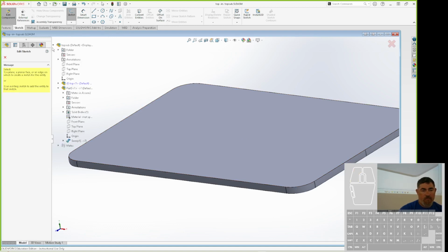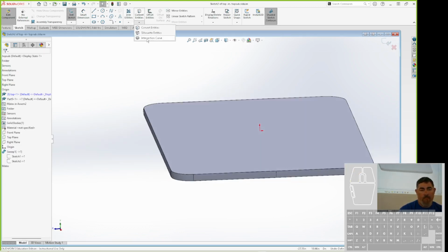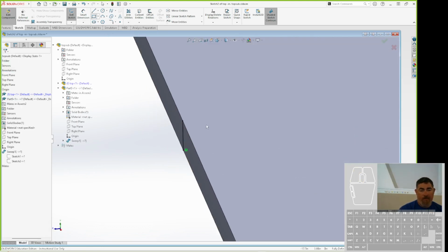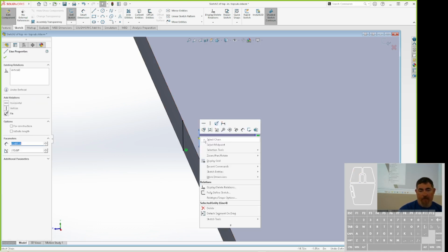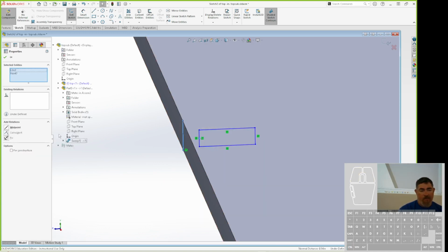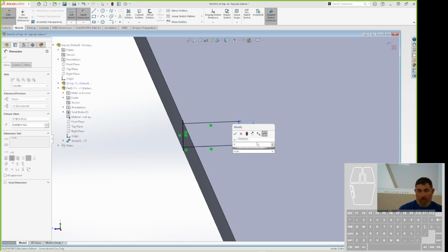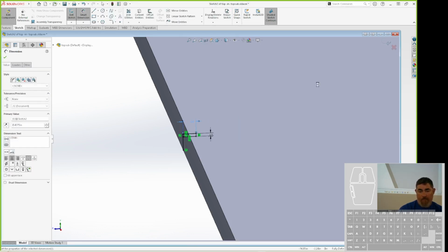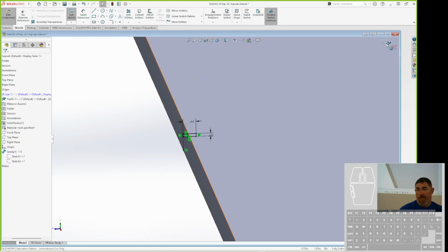Sketch. Over there. And then intersection there. And do my rectangle. And so I want to select the midpoint of this one. Grab that one, midpoint, dimension, said 0.1 and 0.4375. That's my depth. And that line is just going to be a construction line. Finish it.